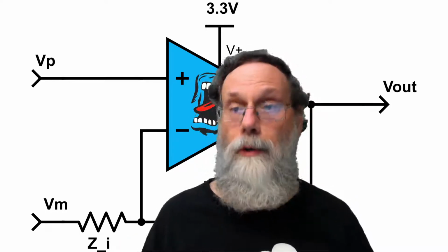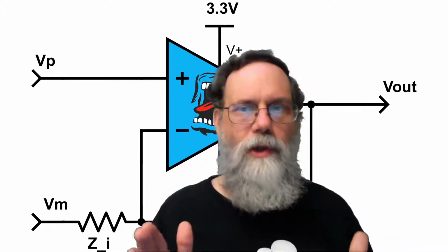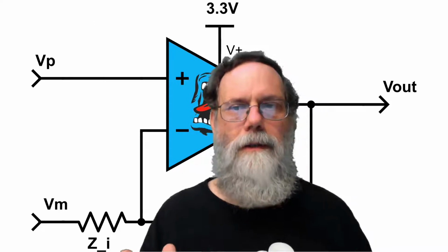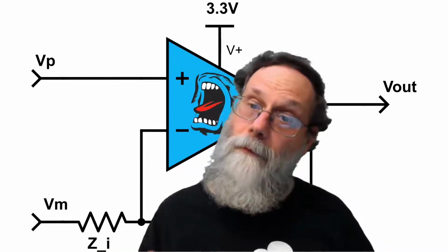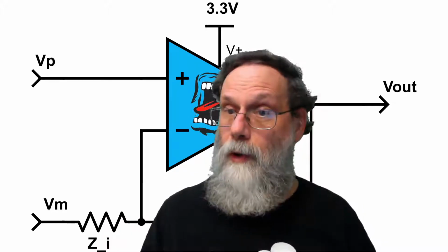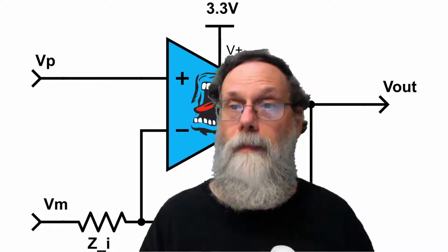Sometimes if we put a large current through that wire, then we start worrying about, well, wait a minute, there's resistance to this wire. The metal is not a perfect conductor. It's not a superconductor. There's a resistance, and so we'll have a voltage drop from one end to the other due to the current flowing through it. So sometimes we have to model a wire as a resistor.